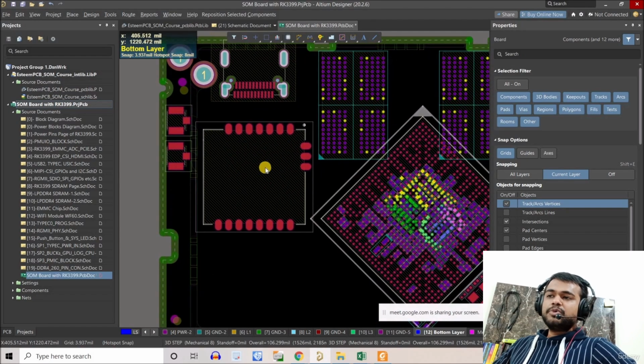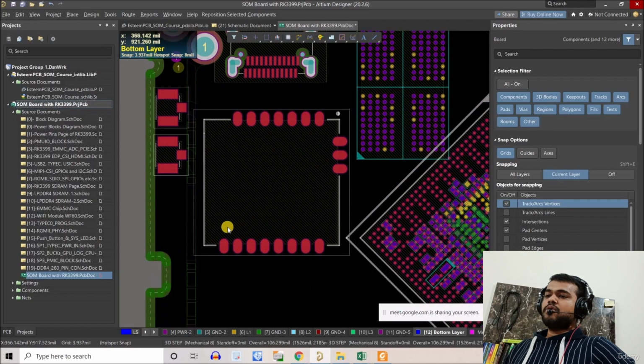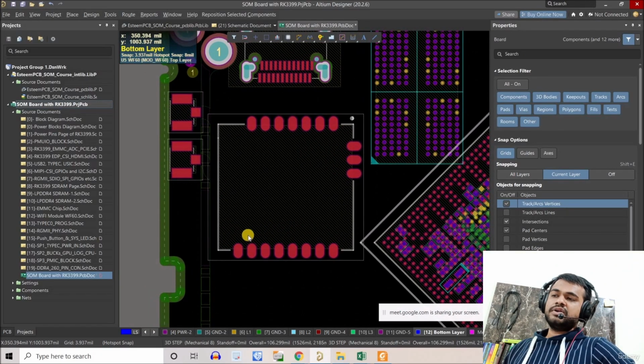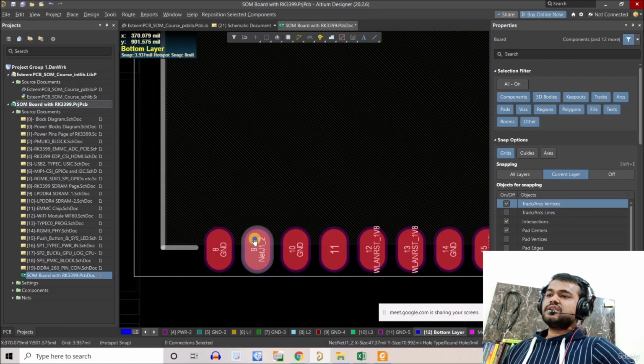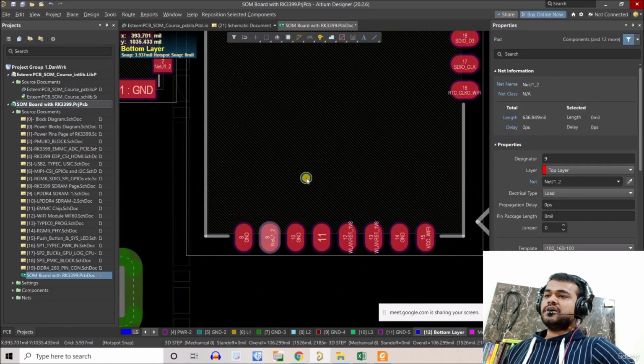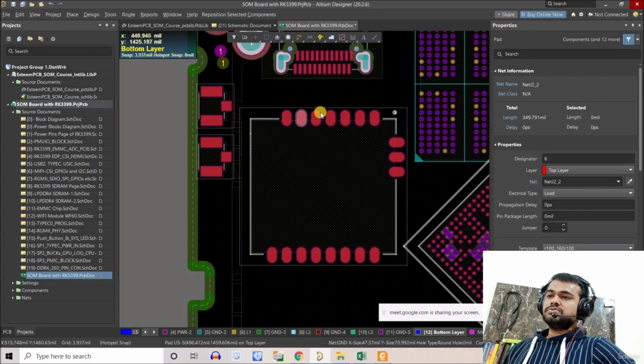For the Wi-Fi module, I would recommend placing all the components under this. See, we have radio frequency connections, one at this corner and another on the other side here, right? So just make sure, because we have to route these tracks. My plan is to route one like this and another one like this, on these two connectors.